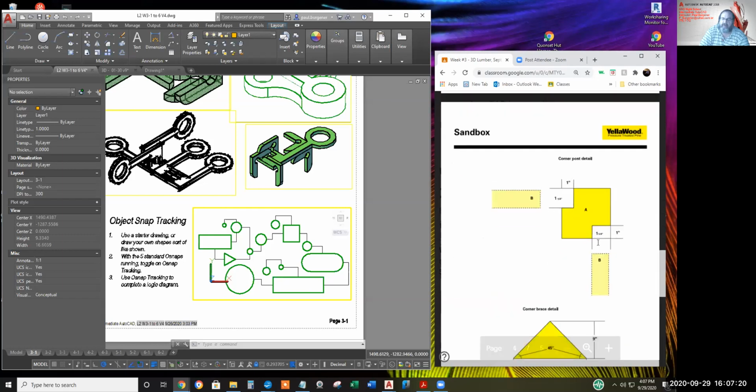Well, it occurred to me it might be a step easier if we just draw this shape with the polyline command, or p-edit join it into a polyline, rather than making it a block and then subtracting out 2 blocks.